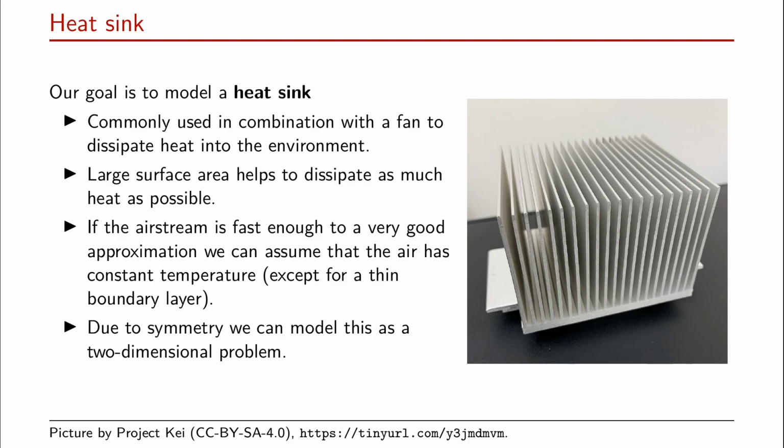So basically the idea is that you have something which generates a lot of heat. This might be your CPU, for example, which is placed below the heatsink, and then you have this type of device whose job is basically to take that heat and distribute it as evenly as possible and to provide as large a surface area as possible to exchange the heat with the environment. So usually there's some type of airflow or other fluid flow, depending on whether this is an air-cooled system or a water-cooled system. So let us assume for now that you have an air-cooled system.